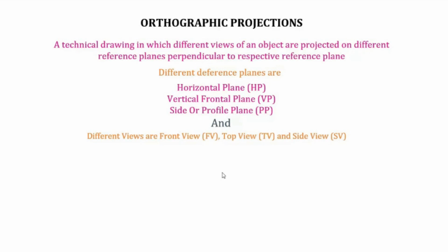They can be used only when some very intricate features are there which cannot be represented in the front view as well as the top view. But in our engineering graphics case, it is not of use because we are not bothered about such intricate shapes. We are bothered about only regular shapes. So don't bother about those bottom views as well as back views. We are bothered about only three views: the front view, top view, and the side view. The side view can be the left side view or the right side view.